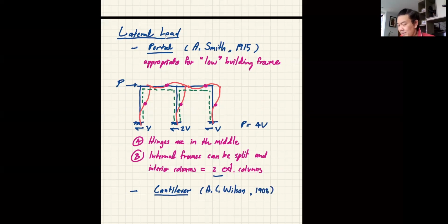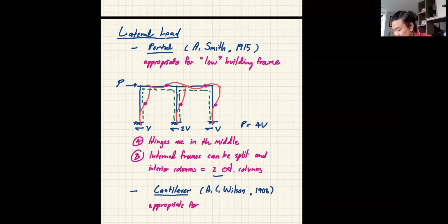So if the portal method is appropriate for low buildings, this cantilever method is appropriate for relatively tall building frames.